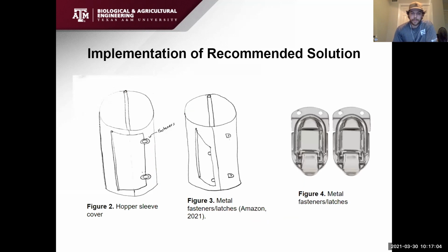The hopper sleeve will be constructed of a pliable sheet metal that will wrap around the spout of the grain truck hopper and be securely closed by metal latches. This will seal the grain and dust inside the sleeve while it falls into the remainder of the unloading pit system. The sleeve will be positioned flush with the truck's hopper and the grates covering the unloading pit below the truck. The sleeve will have 2 hinges on both sides in order to attach to the hopper, remain flush with the hopper and grating below, and attach and detach with relative ease.